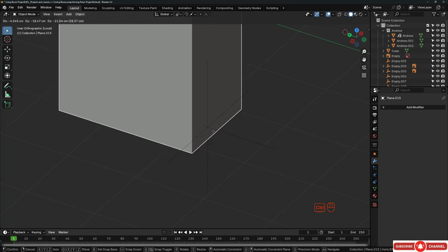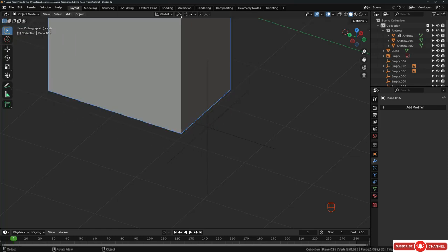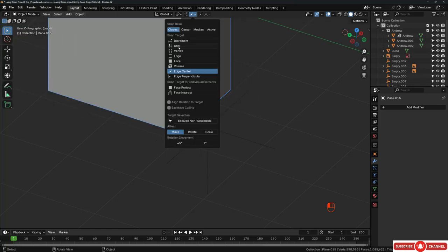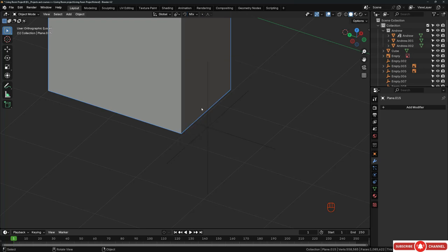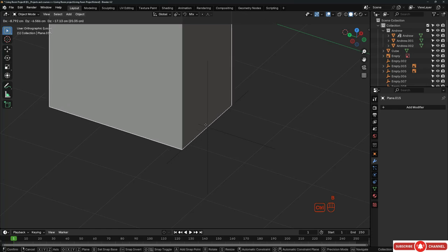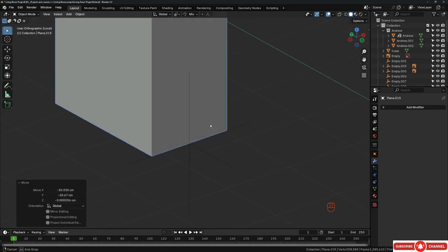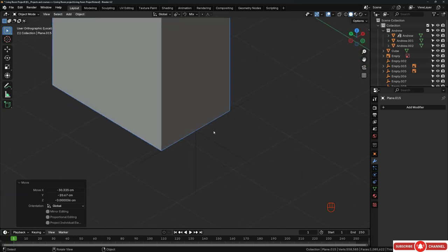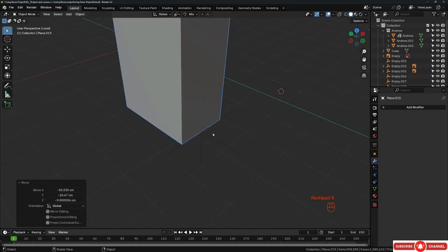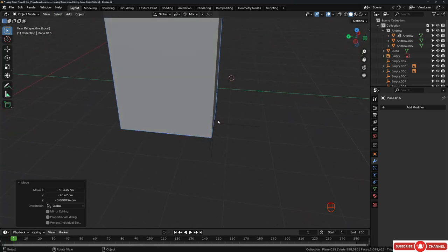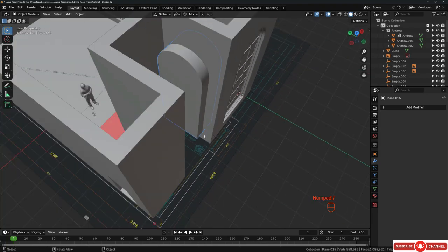All right, doesn't work. That's weird. It should work. Let's activate the vertex snap as well. Hold Shift and let's activate both of them. And now let's do that again. Hit G and then B, hold and grab this, hold control and snap it right here. Or sorry, without control. It seems like it's not necessary. Hit 5 to exit the orthographic view, and now we got this perfectly in the correct place.